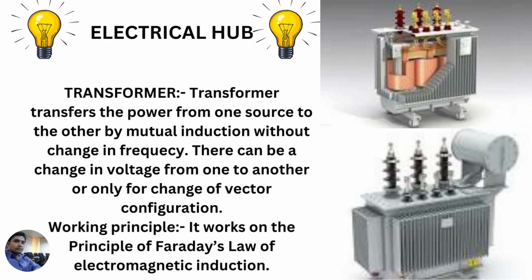First, let us start with the basic of transformer. Transformer transfers the power from one source to the other by mutual induction without change in the frequency. Basically, transformer is used either for the stepping up of the voltage or stepping down the voltage, but sometimes it is also used for the change of vector configuration. For example, from DYN11 to DYN1 or anything like that, or from delta to star like that.